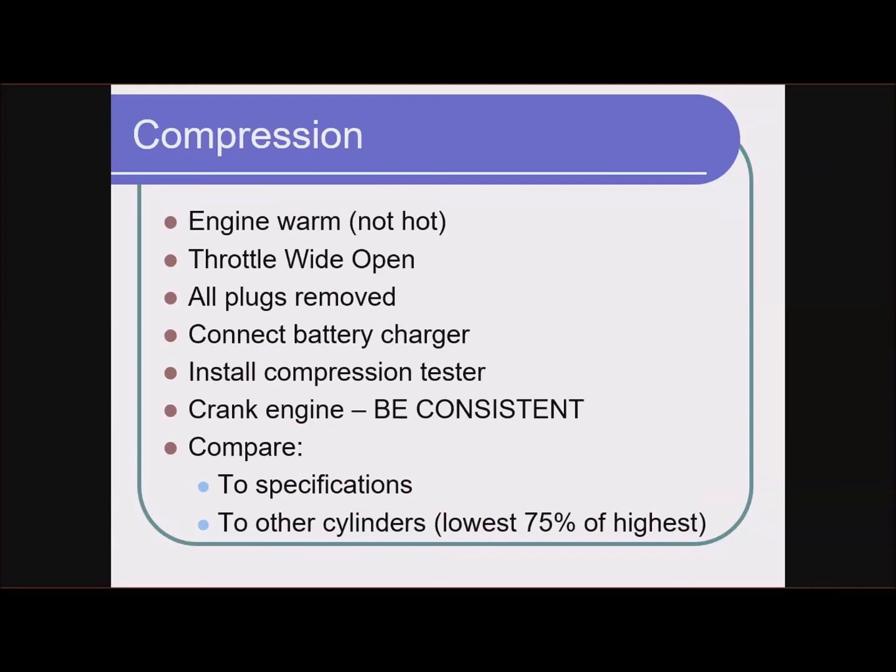I used to tell my students that opening the throttle as opposed to closed throttle didn't make that much difference on a compression test. But I always make the students do it both ways. See what happens if you don't open the throttle. See what happens if you do open the throttle.